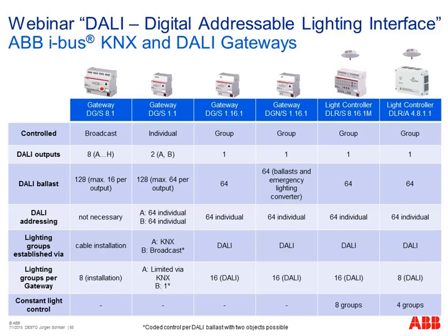So here we need no DALI addressing, nothing. Only connect all your 16 ballasts to one channel, and via KNX we can control all of these 8 channels independently. More flexibility is when we're using this DALI gateway, the DGS 1.1.